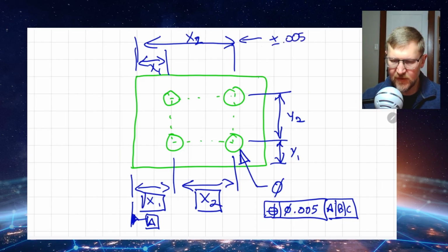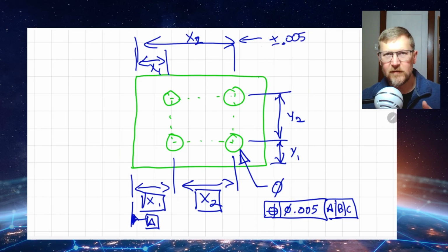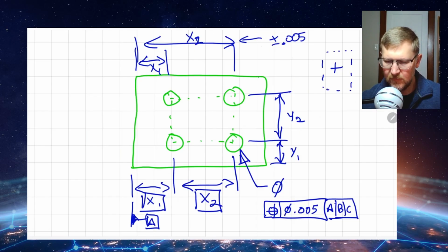And if I say that's 5/1000ths of an inch, if I were to zoom into the very center of that hole and where that hole is located, that means the hole could be up to 5/1000ths in either direction, right? So that's 5, that's 5. It could be vertically 5 up or 5 down. And these are in thousandths of an inch.